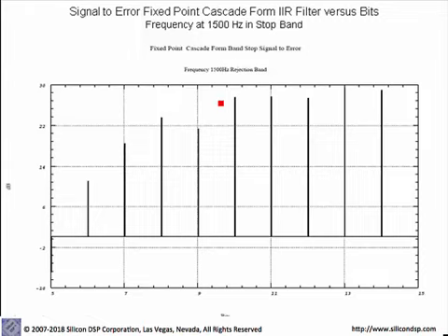In many cases, the filter would be implemented in an end-to-end communication system, and using Tcl script we can actually vary the parameters for the fixed point implementation of the filter in order to meet, for example, our bit error rate requirements, and hopefully come up with the least number of bits or word length sizes in order to meet the requirements, thus resulting in lower area, for example, in an ASIC implementation. Or you might have a fixed point DSP, and you can use the fixed point DSP word lengths in the parameters for the filter design and make sure that you meet your requirements.